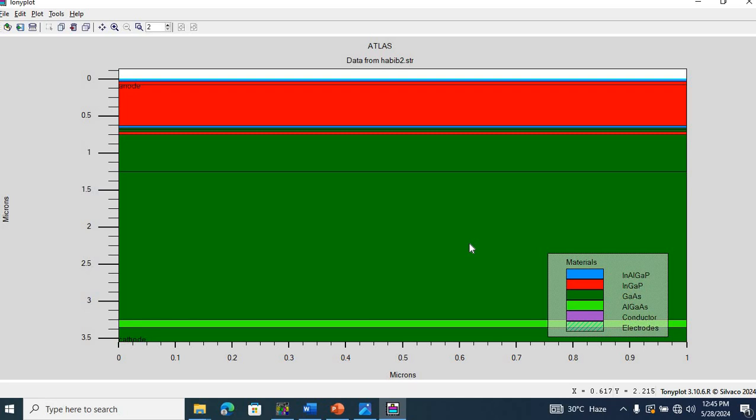This window layer plays a critical role in enhancing the efficiency and performance by facilitating the light transmission from the top cell to the bottom cell, by allowing charge carriers to flow through it, and by contributing to the bandgap or effective bandgap engineering of the structure.